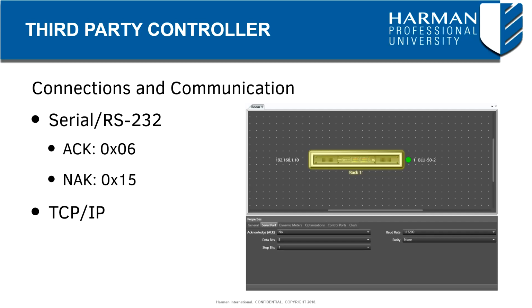SoundWeb London devices listen for messages on port 1023. Control messages can be transmitted to a single SoundWeb device or multiples. However, it is only necessary to establish a connection to a single device on the network. Messages intended for other SoundWeb London devices will be forwarded as necessary.